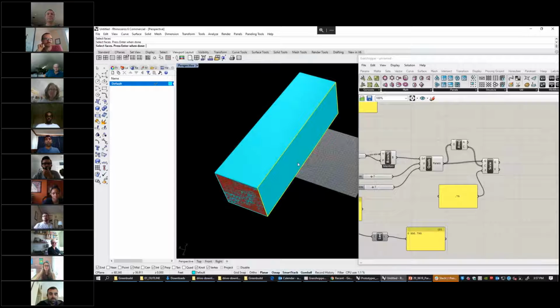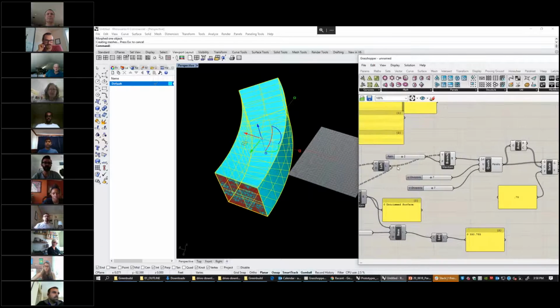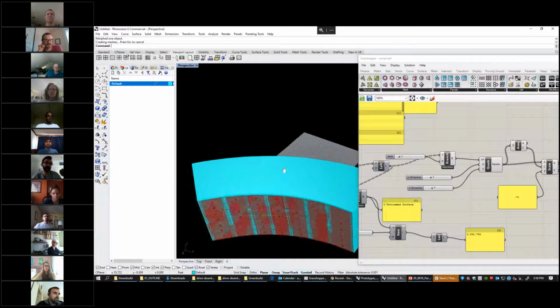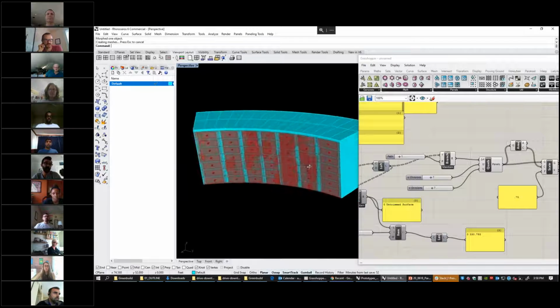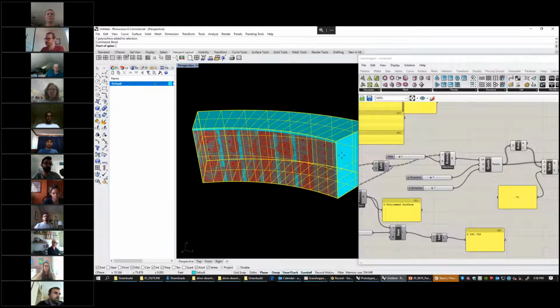Or you can rotate. I'm just trying to curve this one. The way that I've done it is with any curvilinear surface. The one that I made is pretty complex because it was double bending, in both directions, U and V in Rhino, and similar to what Anish is doing on screen right now. Maybe this is a better example.